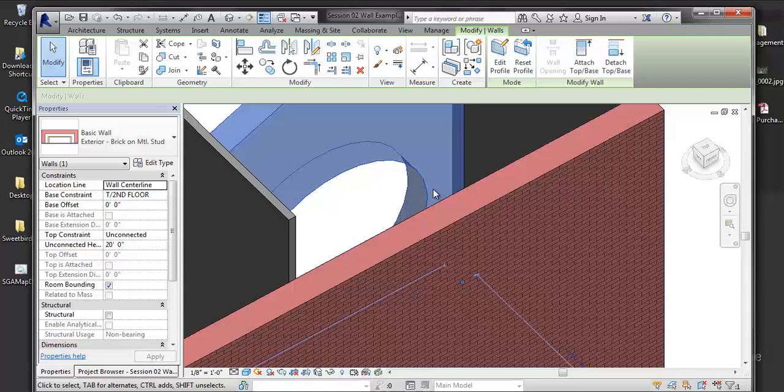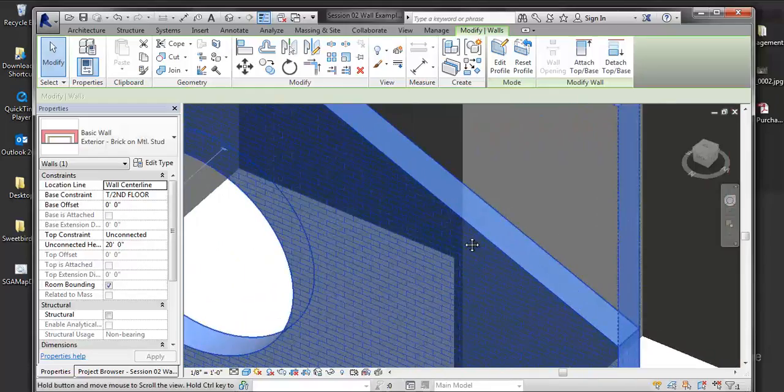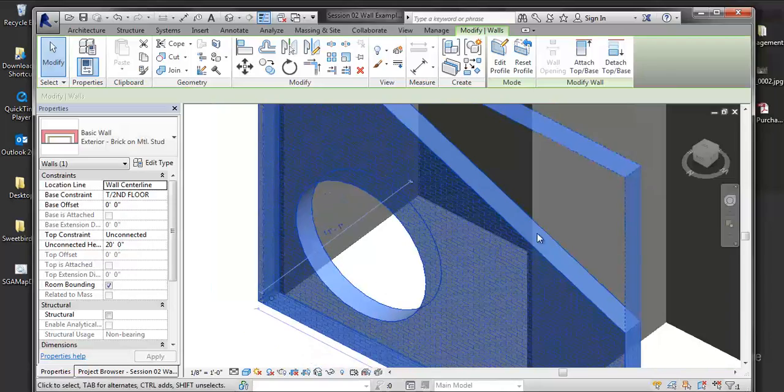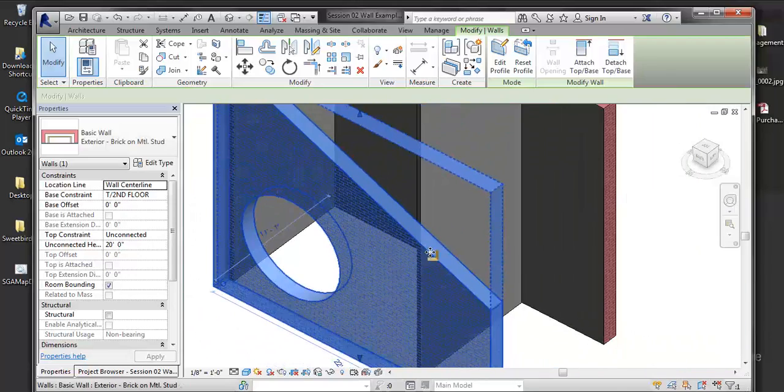So, what you're talking about, I think, is a higher level of detail for rendering than what's built. There are different ways to do it. If I wanted that to look a certain way for a reason, I would build it differently. I'm assuming what you described was a soldier course around the circle. I would model that even in place, as a collar wall. It gets you 85% of the way there.